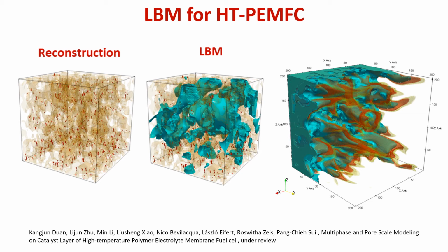On the other hand, ionic conductivity of the catalyst layer depends on the amount of phosphoric acid. Therefore, it becomes an optimization problem, and simulating the movement of phosphoric acid is helpful in providing insights into the problem. On the right, it shows the fluid viscosity would affect penetration.